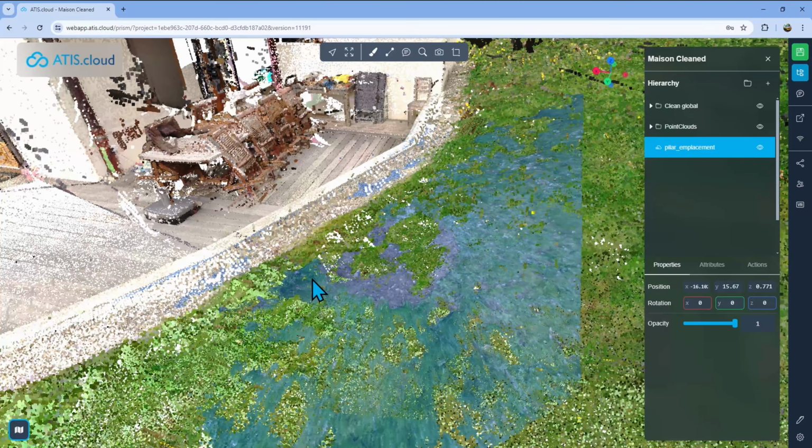Okay, so if we take a look at this, we can see that solar panels can come in very different sizes. So I have like 1 meter by 1.7, or 1 meter by 2.1, 1.1 by 2.3, or 1.3 by 2.4. I believe I'm going to use this one, the 1 meter width, so it's easier for me to make the calculations, because I know that each panel is 1 meter of width, and also I have a 1.5 centimeter difference between each panel, and then it's approximately 2 meters high, so same thing, it's going to be pretty easy to make the calculations. So I'll use this one, okay?